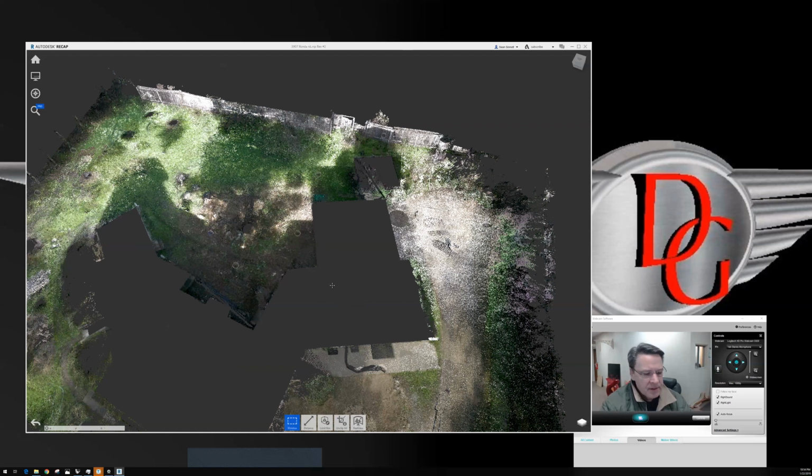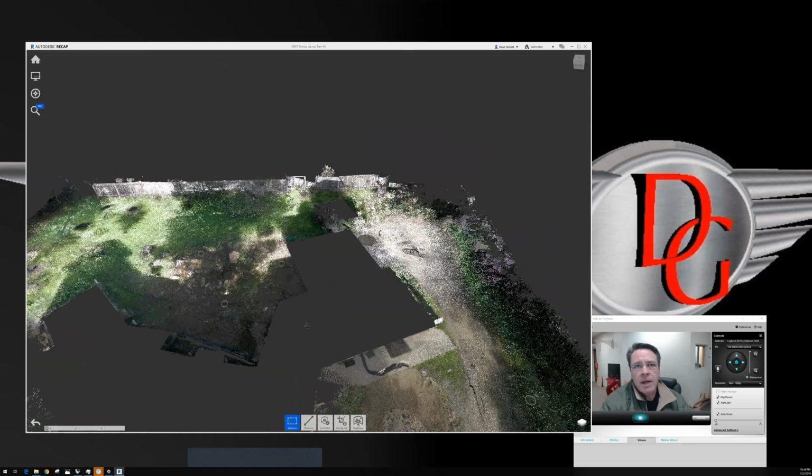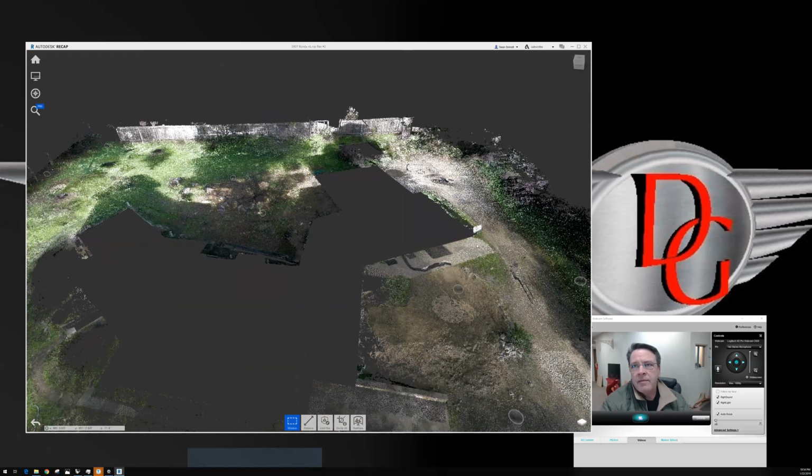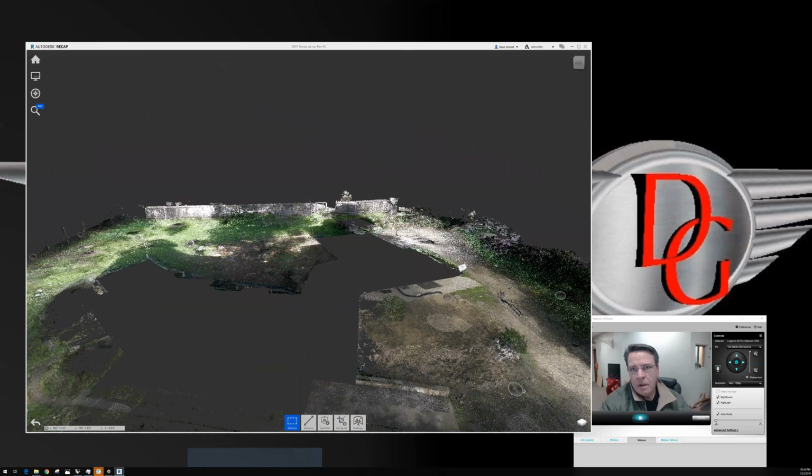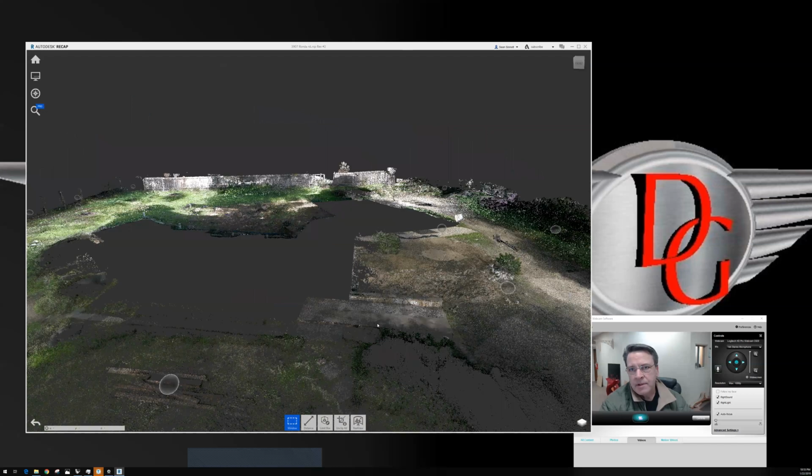A couple of things that we went ahead and did is we identified where the slab is, this curb, the walkway leading up to the stairs where the front door is. So we generated all that flat work. We've got the perimeter foundation. So what we did is we created a ground level at the floor height.